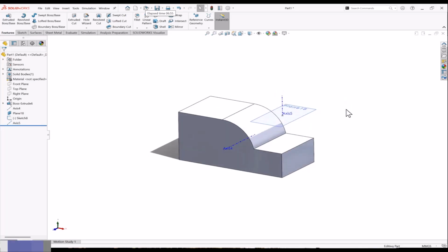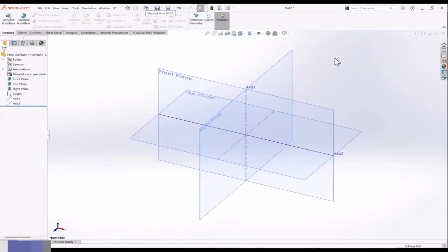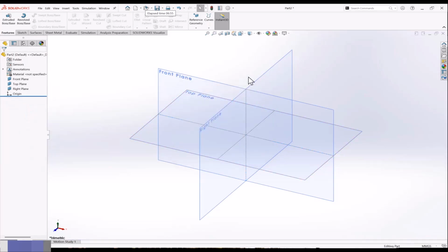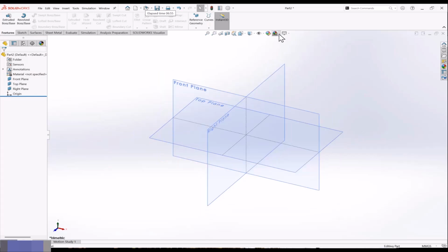Now let's come to 2D sketching and 3D sketching. What are the differences? Whatever sketches we have made till now, in the previous sessions, are 2D sketching. Now 3D sketching is where we don't require any plane. We can draw directly without a plane, using the tab key. I don't need to take a plane actually.